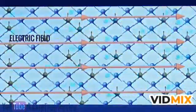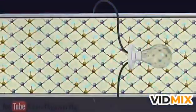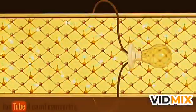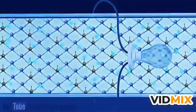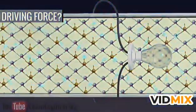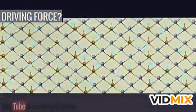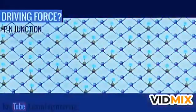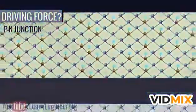Let's try to make a highly simplified solar cell only using this type of material. When light strikes them, the electrons will gain photon energy and will be free to move. However, this movement of the electrons is random. It does not result in any current through the load. To make the electron flow unidirectional, a driving force is needed. An easy and practical way to produce the driving force is a p-n junction. Let's see how a p-n junction produces the driving force.